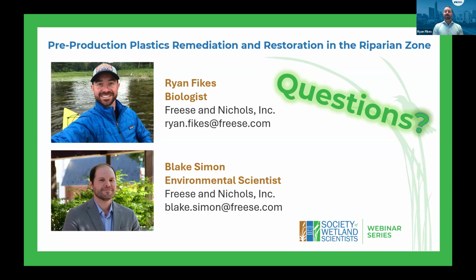So what we're seeing to reduce things from a stormwater component is, and I can use our client as an example, they're developing numerous large-scale evaporation ponds that all of their stormwater goes into and then has a filtration tube before it leaves their production security perimeter of the facility and would enter the public environment. They're still working on getting that fully functional, because during a high rain event or a storm, they typically exceed the capacity of that and therefore end up with a release, like I mentioned, that we've had 11 of them. Those have all been centered around high rain events. But yeah, now it's that overflowing of stormwater evaporation ponds, but also poor housekeeping.